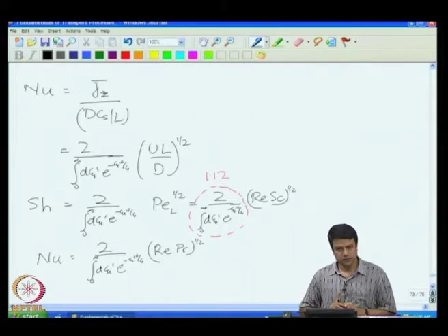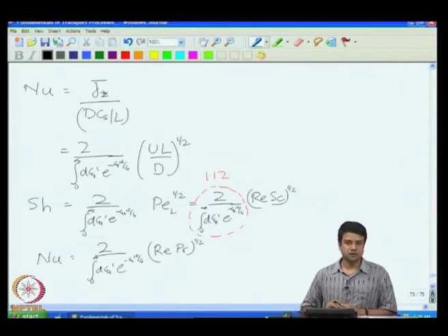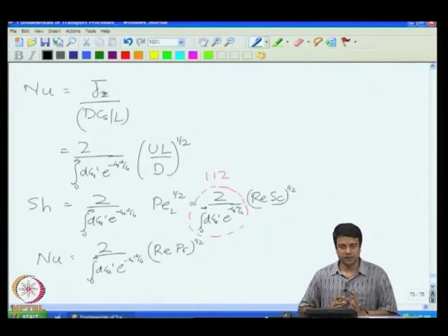Not a similar analogy for momentum transfer, because we have to have body forces acting on the system. We will come back to a momentum transfer problem a little later. So, that was a class of solutions called similarity solutions, where effectively I have transport into an infinite fluid, and I use that fact to reduce the problem based upon dimensional analysis or analogy to a dimensional analysis problem, and then use that to get a solution.